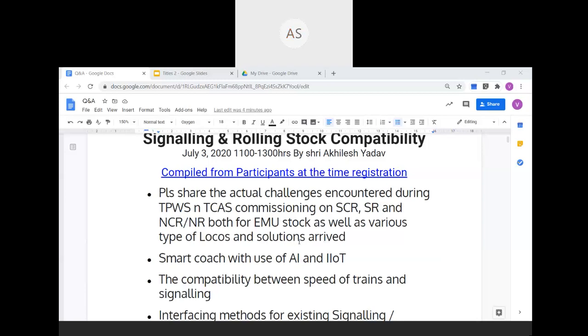Just to add to what Akhilesh mentioned, there is also a very strong standardization of the wiring protocol on the locomotive, which is important from the angle of being fire resistant and slightly less prone to EMI within the system. The second issue is the mounting of the tacho generator, which requires a spare axle to be made available for that purpose. Thank you, sir.